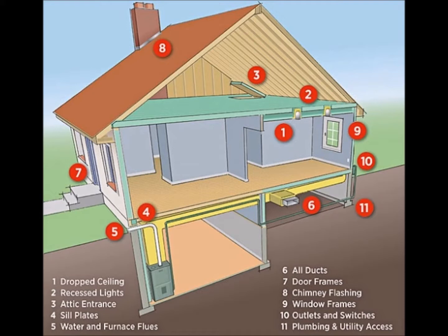Use of airtight poly methods should be applied more cautiously, as some experts have concern that the poly layer is almost too airtight and vapor impermeable, and will not allow drying to the interior of the building at any time of the year. Conditioned interior spaces should be maintained at low moisture levels.